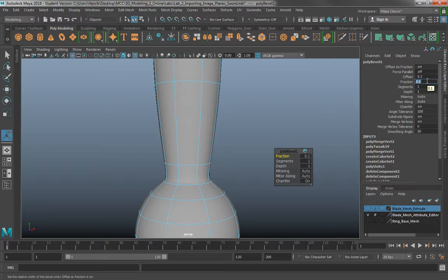We call it, give me one second, hard poly surface modeling. So let's go, I think 0.2 is okay, and this offset doesn't seem to be doing much, so I'm just going to leave it at 0.2. And segments 2, and you'll see how that gets that harder edge. If I make it 4, you'll see it gets a lot tighter in here, and as you subdivide it more, it'll maintain that hard crease much better.